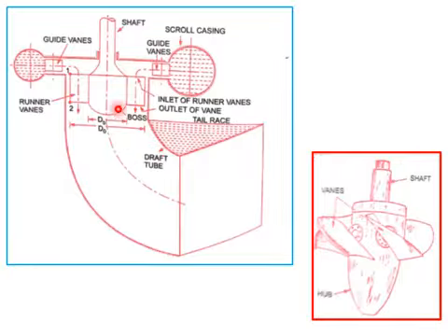This is the sketch of an axial flow turbine. Water from the penstock is brought to the casing. From the guide vanes, water is thrown to the runner vanes. Here in this case, it consists of something like a hub where there are 4 to 6 vanes which are mounted onto this hub. So that is what is shown.